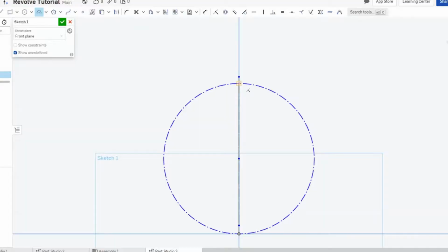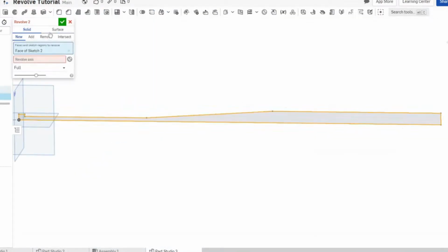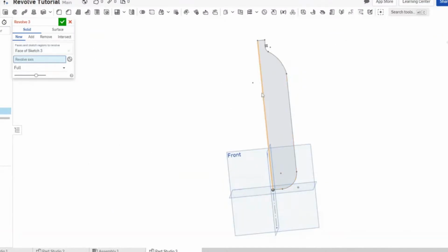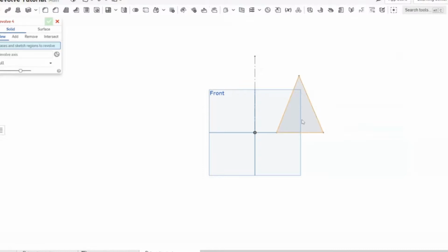Today we're going over the revolve feature in Onshape. Revolve is useful for anything that is circular in nature or symmetric about an axis. A ball is a perfect example. A baseball bat, a 2-liter bottle. These are the types of things where you draw an axis, you do half of the geometry, and you sweep it in a circle. We'll show you how to do that.